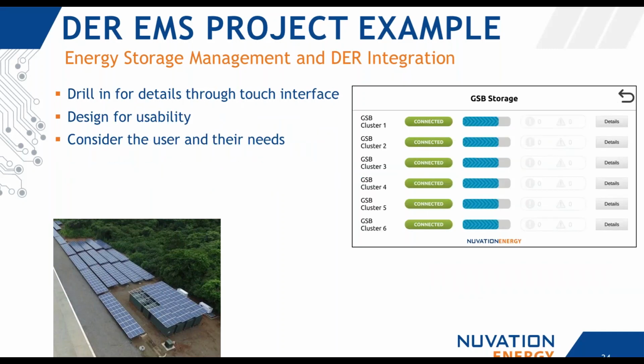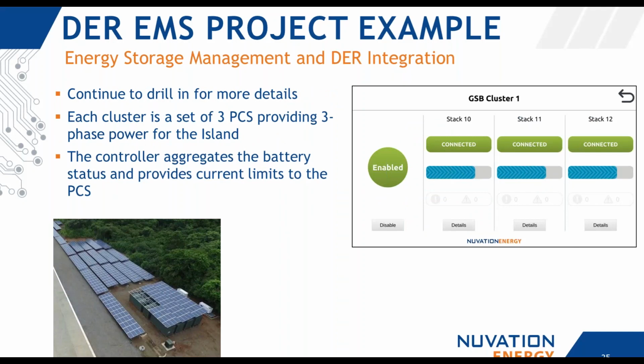This custom dashboard, Nuvation designed it for the user. So it was a touch screen. They could easily drill in to see individual parts of the system, how well they were behaving, if there's any alerts or warnings that needed to be dealt with, and they could continue to drill in for more details. In this case, we had organized things in clusters. A cluster is a set of stacks to support 3 PCSs that work together to form 3-phase power for the island.